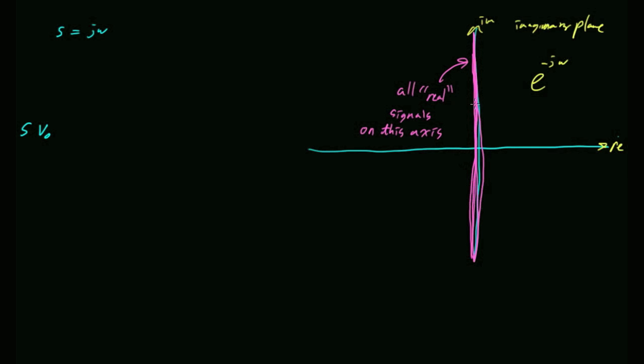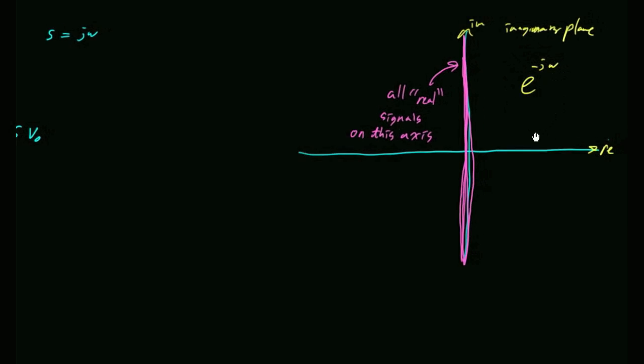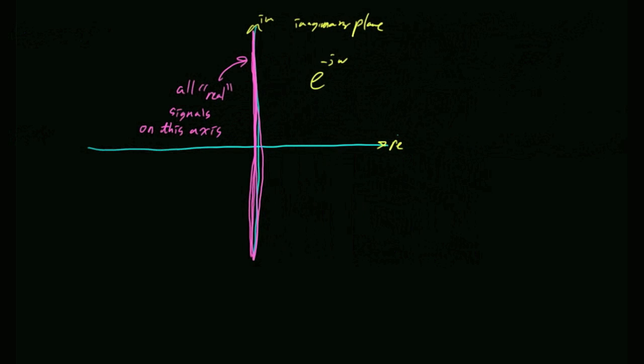That's the Fourier transform. The Laplace transform talks about e to the minus st, where s equals sigma plus j omega. So the sigma is a real part, and that gives you frequencies that could be anywhere on this plane. Yes, sir? But when we take the Fourier transform, sometimes it's shifted, right?